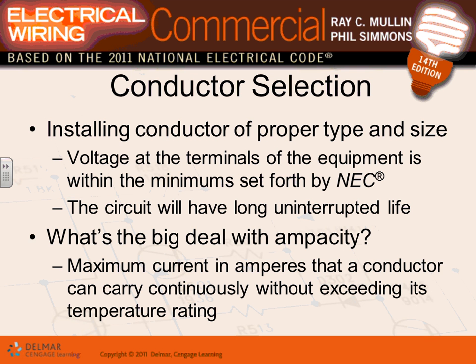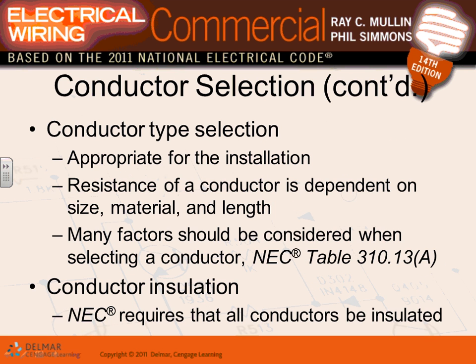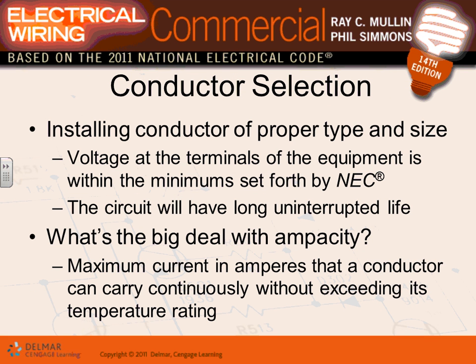Okay, so that's conductor selection. So a couple of things, guys, for conductor selection. The first thing is continuous load. Temperature: if the temperature is different, you also have to derate based on temperature. And also voltage drop. You have to take into consideration voltage drop. We will be doing voltage drop calculations for branch circuits.